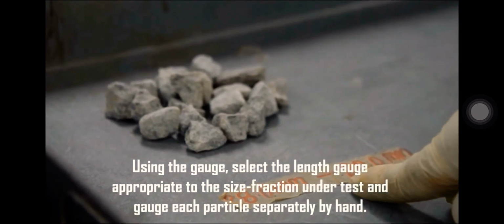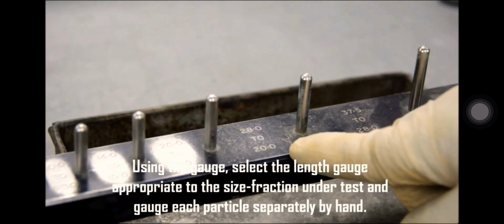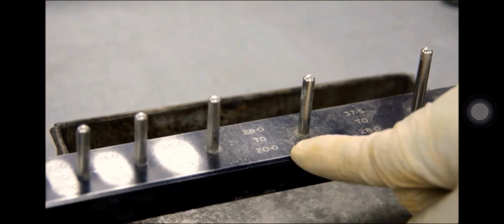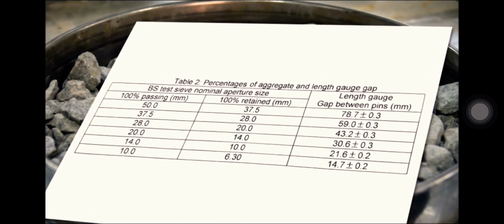Using the gauge, select the length gauge appropriate to the size fraction under test and gauge each particle separately by hand. Refer to Table 2 of the Highway Laboratory Test Manual.